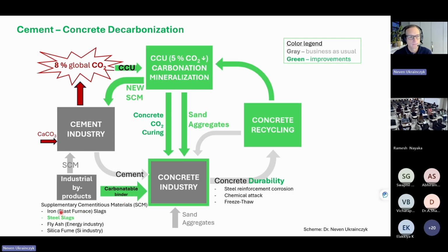They have a lot of gamma C2S, which is not hydraulically reactive, but under CO2 or acid conditions it is very reactive indeed, and they then form silica gel, calcium carbonate and some CSH gels. This is then the new carbonatable binder that can also harden using no cement at all.